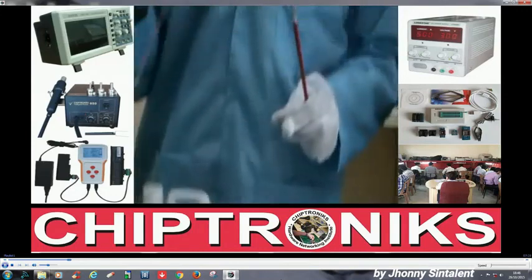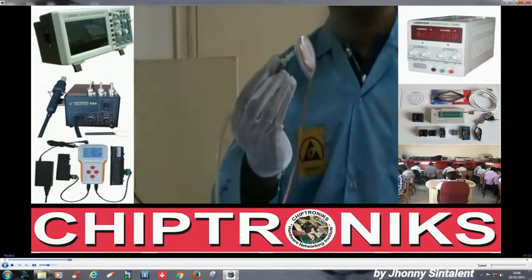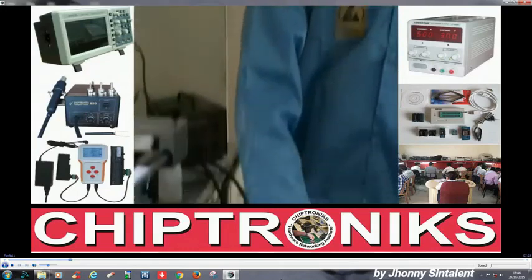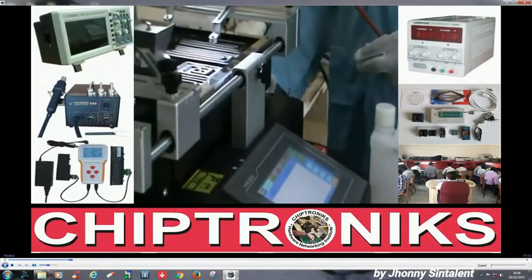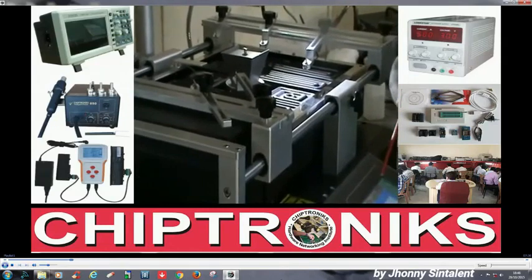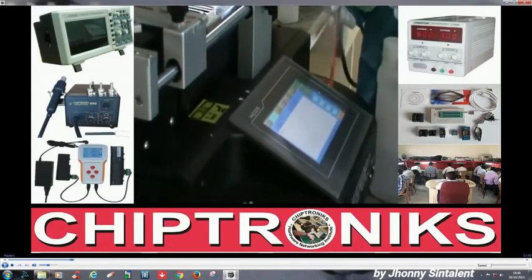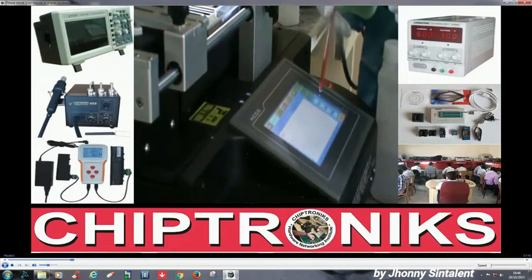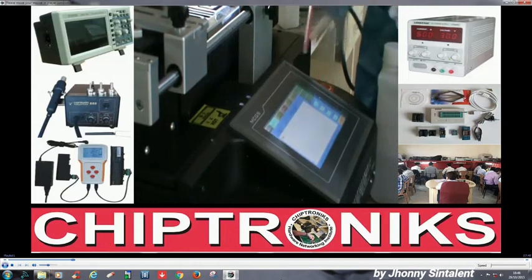And you can see, we can pick up this desoldering wire via this vacuum picker. So it has an excellent capacity to press to pick up a BGA chip. And now we can see there is temperature showing up on the side. This is first, second, third and fourth. This outside is for you.